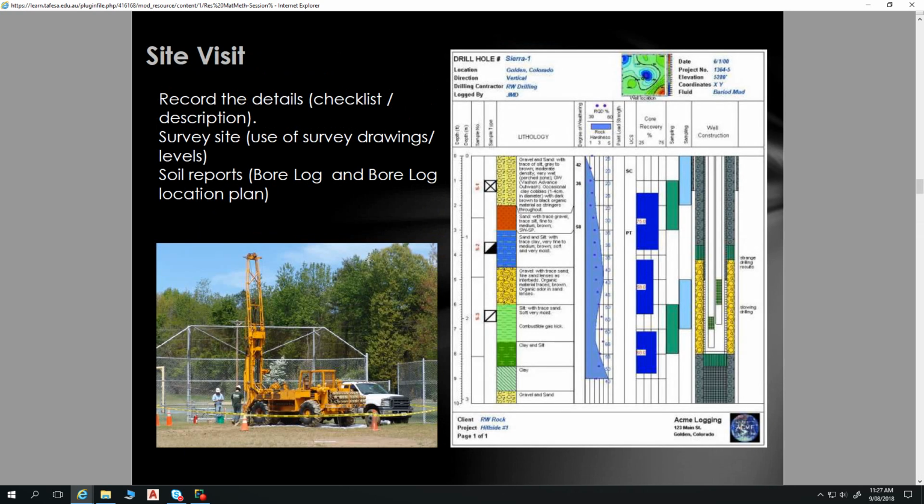So basically, what you end up with is this long cylinder of soil. The soil sampler will pull their stainless steel tubes out and tap the soil into boxes, and then the engineer who's producing these bore logs can look at that soil and say, this is the type of soil it is, and they'll classify it into various different classifications.